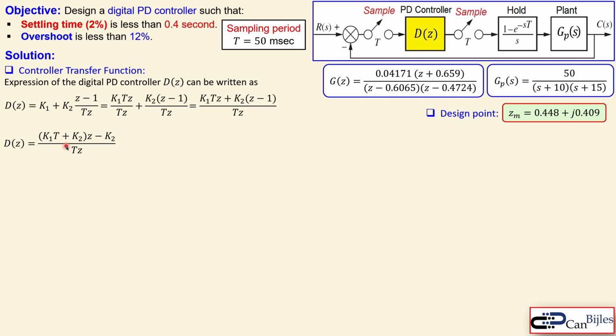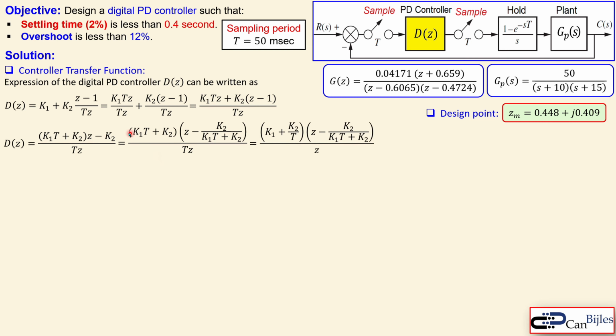In order to see the expression clearly as the gain and the zero and the poles, we can combine the terms which are in Z. So these are here, and this is just a constant. Now we can rewrite this further to get this expression. So we now recognize directly what the zero is here. We can go even further by dividing out the T here, so we can now recognize also the pole directly. That's shown here. So we divide the numerator and denominator by T. That's only this part. And we have now this expression.